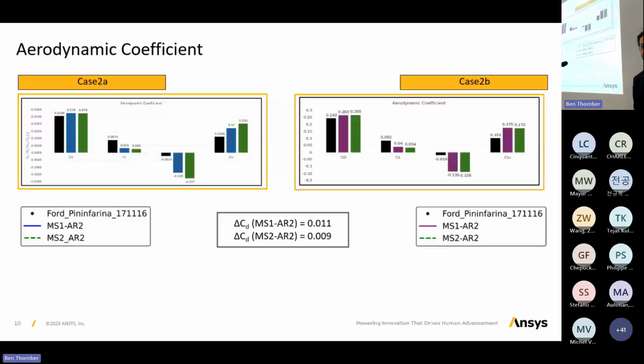Okay, wall function LES comparison. We're not entirely happy with the results we have, but that's what we did get so far. 0.27 for drag, which I think is the most relevant quantity. The mesh refinement did not actually make a big difference here. Actually, no difference at all. I think that is just because the boundary layers are already captured by the coarse mesh, and the refinements didn't go into the region where they should be. So for delta CD, I think we are in reasonable agreement.